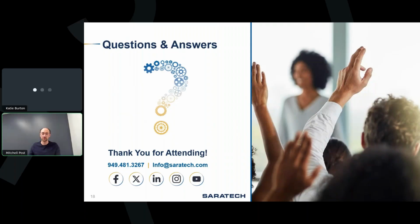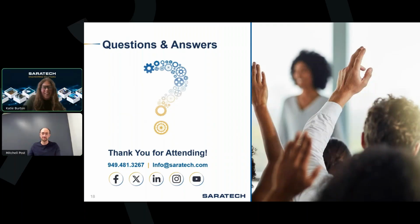All right, on to questions. Awesome. Thank you so much for walking us through all that. We have two quick questions. Can elements of all types be used together in a solution? Yeah, you can use 0 to 3D element types all together. You just have to be aware that you're creating the right connections with 1D connections or other commands. So just be careful and make sure, and always double check with your math.